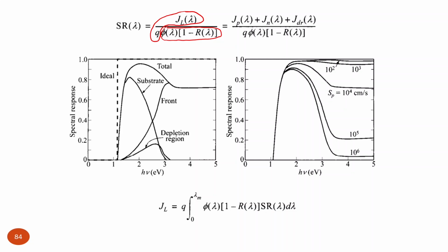So keep your attention on "absorbed", because we have the total flux, that's the number of photons which hit the solar cell. But here we take into account, we subtract those which were reflected. And that's why for spectral response or internal quantum efficiency we consider the ratio between total charge carriers which form photocurrent to the total number of photons absorbed by the solar cell. And that, of course, is at given wavelengths, because we have a spectral distribution of this internal quantum efficiency.